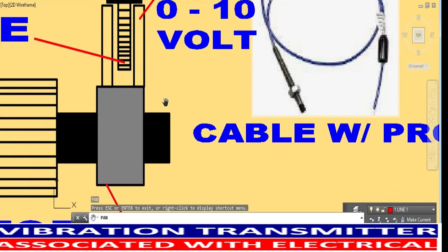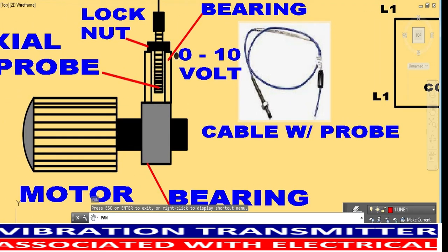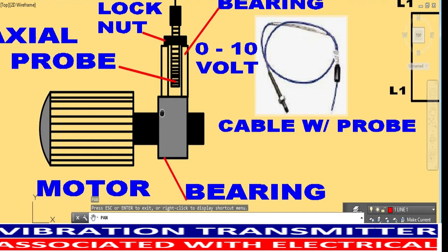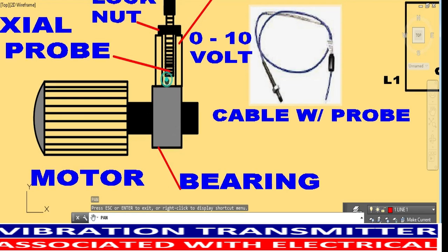And here is how the motor is protected from vibration. During the running of the motor, this shafting is driven by the rotor of the motor. Once there is an abnormal condition of this shafting, because of the bearing or the rotor condition or whatever, the vibration will be high. That's why this motor is protected by the vibration probe.